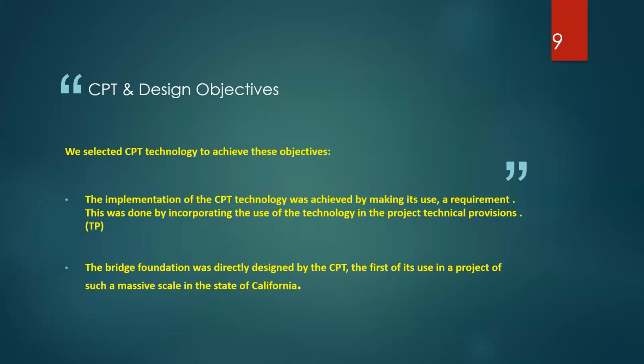Of course, when you do that, and speaking of design objectives, you have to have, as I'm sure you can understand and appreciate, a keen understanding of the local geology and conditions at your site before you apply this mandate in your TP. So as I mentioned earlier, the objective was to investigate and characterize the site, each bridge, by a combination of CPT and borings, but the CPT basically dominated the profiling, and also the direct design of bridge foundation. That was not mandated in the TP.